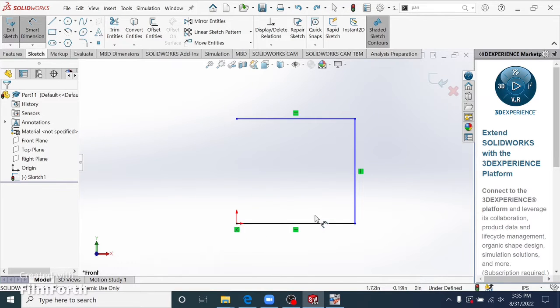And you notice these green icons that turned on. It means that some of the icons will be telling you what features it's going to include. So for example, just right here with the T or intersection, it means that it is perfectly perpendicular. In the software, you can't really tell, but on there, it'll say this is going to be 90 degrees and it's going to be perfectly 90 and 90 from both sides.